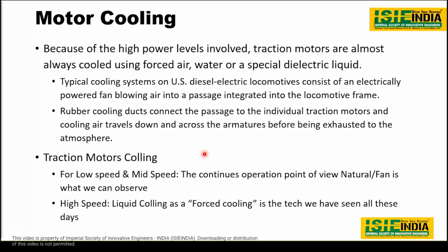In the mechanical side implementations, right? In the natural cooling, cooling fins will be there in the stator of the motor, right? And after the rotor, right, there will be fans. That is forced cooling actually, okay? But most of the time, that is also treated as natural cooling, okay? That depends on the application actually, right?